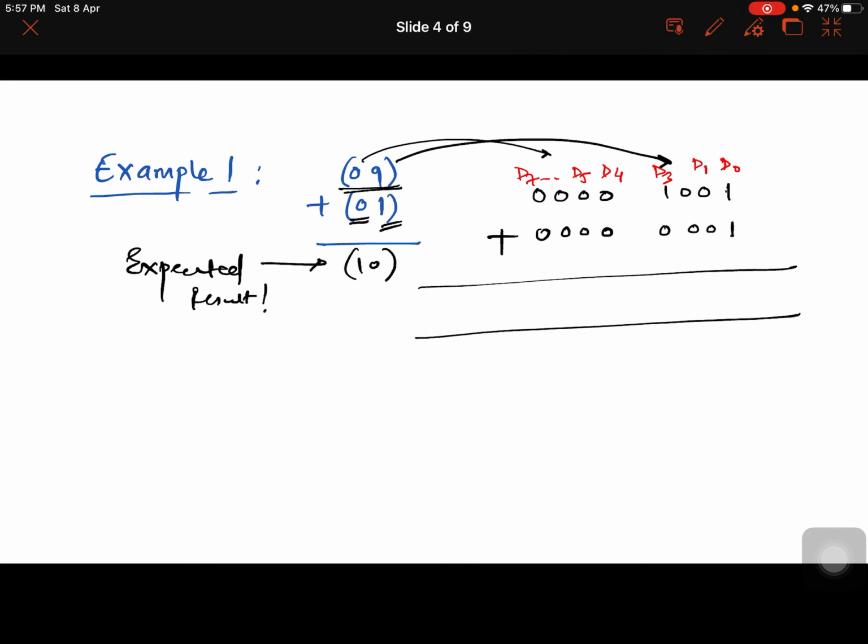So what is 1 plus 1? It is 0, carry 1, then it is 1, then 0, 1, then we have 0, 0, 0, 0, right? So this is our actual result. Now since every number is treated as a hexadecimal number, naturally this is treated as 0 and this is treated as A. And what really gets displayed on the screen is 0A. Am I right? Then I told you the DAA instruction helps to convert this 0A into 10, and let us see how it does.